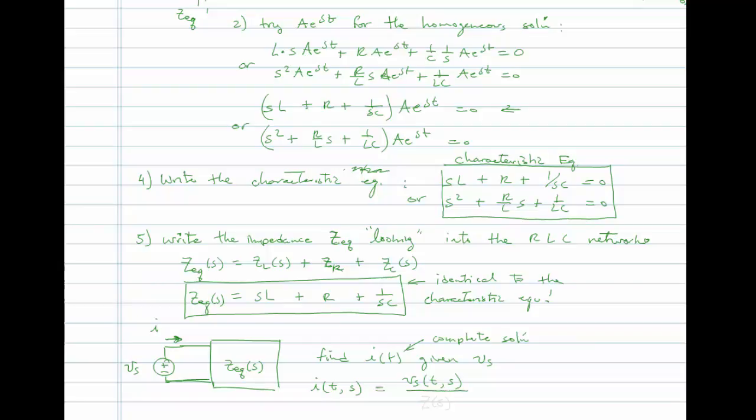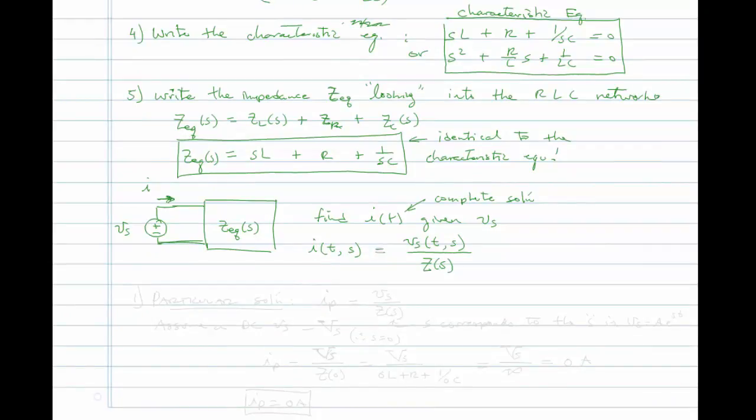We're going to take that voltage and we're going to divide it by the impedance. And we write Z sub s because, as we have seen before, like when we looked at the individual elements, we saw that the impedance, for instance, of the capacitor, 1 over sC, is a function of the form of the signal that you're forcing it with. If you force it with a constant voltage, i.e. s equal to 0, then the impedance is, in fact, infinite. But if you were to force it with a signal that had a very large s, then the impedance would tend towards 0. So, we're going to see how far we can carry this analogy to Ohm's law.